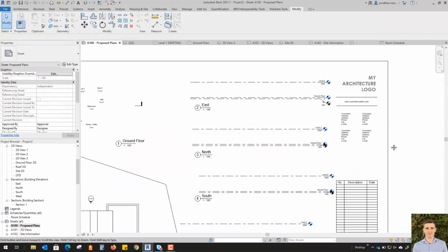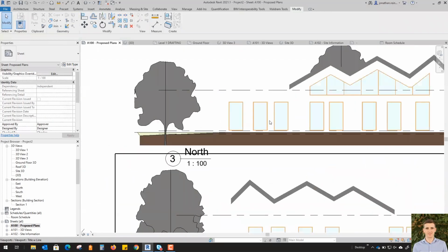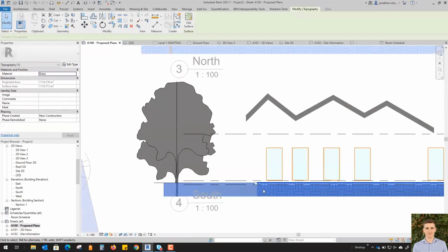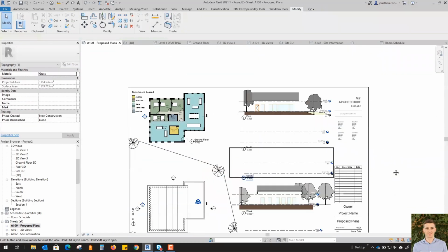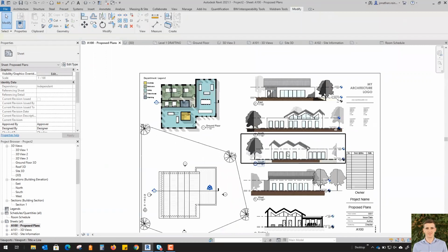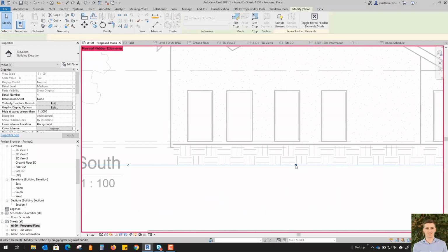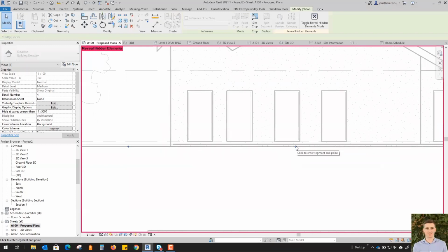As you tidy up your drawings, you will find yourself maybe using the crop region per each view, and this is engaged just by double clicking into a view and just going down to the bottom left of your toolbar beside the scale bar and just turning on your crop region visible. So you just select that option and you can simply select it, the actual box.